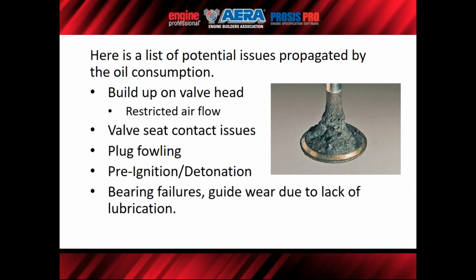Here's another list of potential issues propagated by oil consumption. Again, with direct injection, there's a lot of pictures floating around of ports that are almost completely blocked, so you're restricting airflow. If you get too much of the buildup, then it starts to get between the valve face and the valve seat, so you have valve seating issues, plug fouling. We kind of think of that as one of the things from the past, but it gets to a point where it can happen.